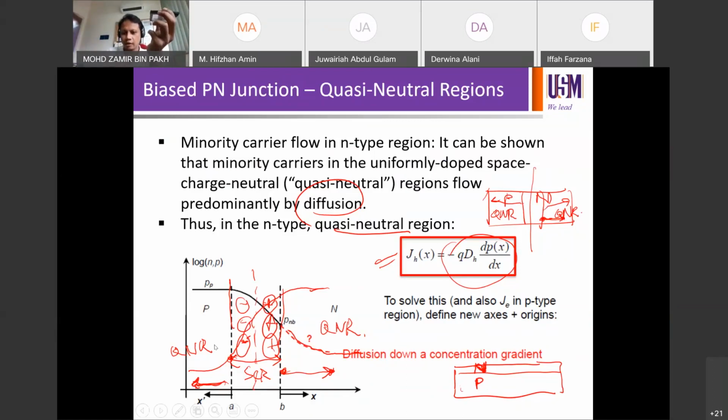that's exactly what we're doing now. Your eyes are here, so you're looking from the side, from the camera. So from the side, this whole thing is P-type, before there is any N-type. Normally when we buy, it's P-type or N-type or intrinsic, if you like. You can also order intrinsic, undoped. Then you can diffuse the first few hundred nanometers of the surface. On the top surface, you can diffuse a very thin layer, like 200 nanometers or so, while the whole silicon wafer thickness is like 200 to 300 microns. Okay, that's 3 times our hair thickness, and you use 200 to 300 nanometers to dope the surface to form this N-type.